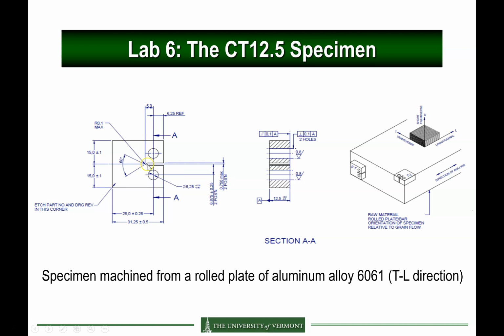And these pictures are taken from the root of the notch. So remember that if you're measuring the crack length from the notch, you need to add 5 millimeters to ensure you get the proper crack length from the center location of the pins here. Okay, so that's one aspect.